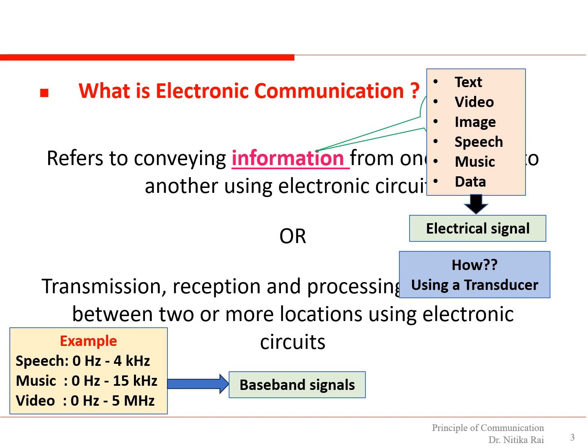So we know that bandwidth is defined as the range of frequencies that the signal occupies, and it is calculated by subtracting the lowest frequency component present in the signal from the highest frequency component. So we can say that speech has a signal bandwidth of 4 kilohertz minus 0 hertz, which is equal to 4 kilohertz. Music has a signal bandwidth of 15 kilohertz minus 0, which is 15 kilohertz. Right?